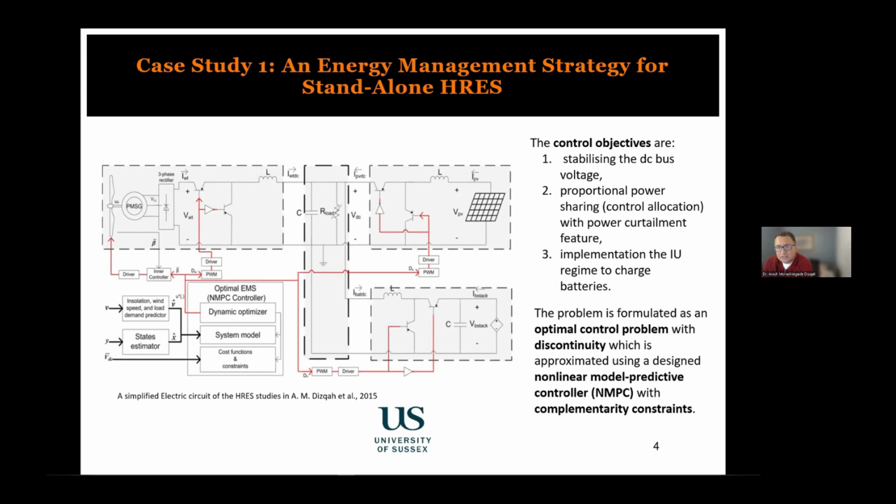Not being connected to the network makes it a bit more complex and challenging from the control perspective, because the grid can be assumed as an infinite capacity battery connected to your system. Without it, all your capacities, and particularly storage capacity, are limited.